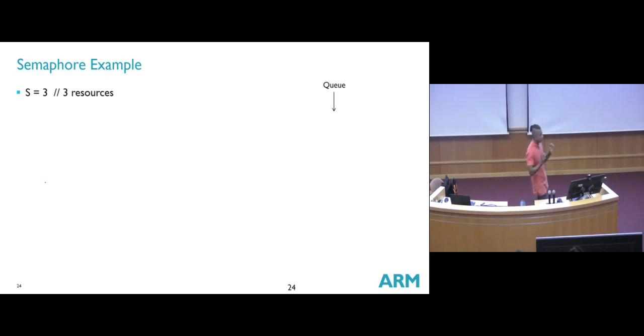Okay, so in a sense, you can think of resources as anything that a task may want to use. Maybe you set aside certain blocks of memory, say 1 kilobyte of memory space, and you have 3 chunks of this. Or you can say I have 3 different timer blocks, and whoever wants to use a timer can use it. Or 3 different ADC channels, and whoever wants to do an ADC operation can request a channel. So a resource is anything that can be shared among different processes that you want to manage.